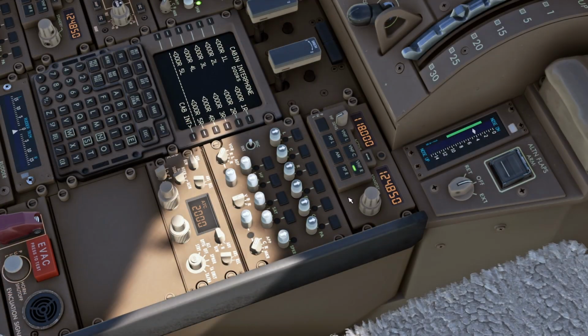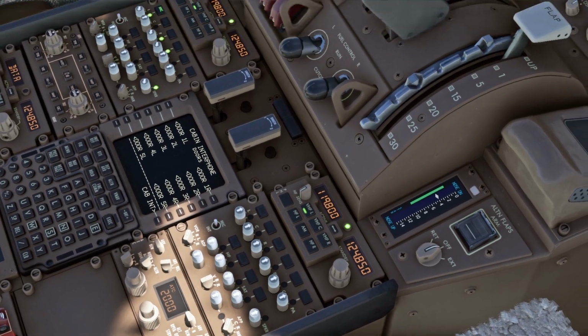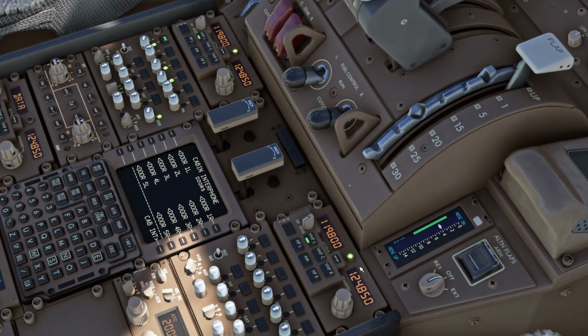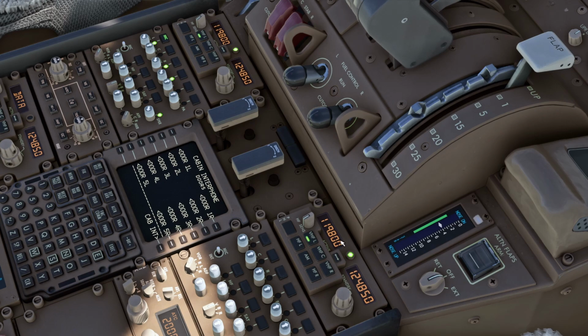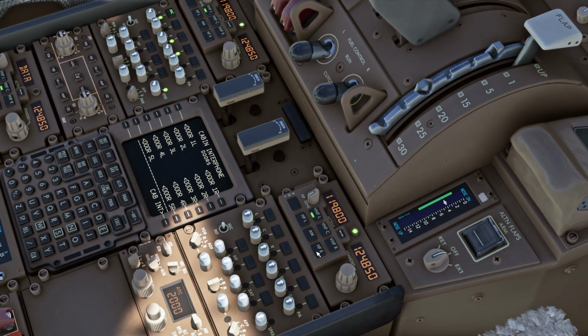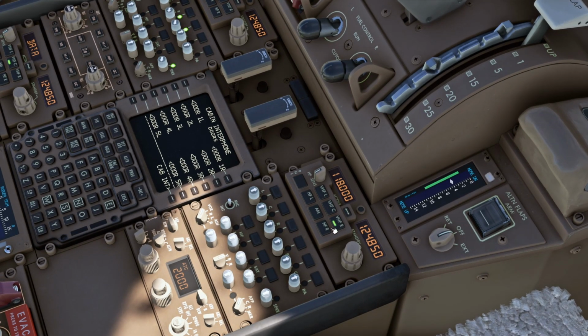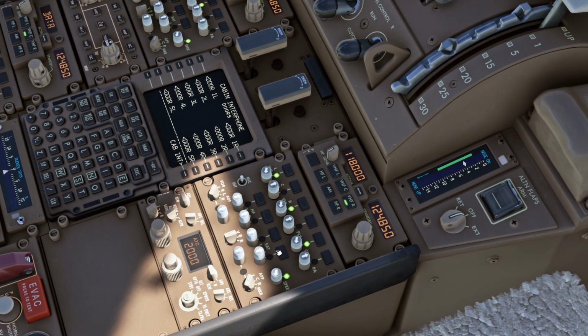Then the first officer radio tuning panel. Adjust to your liking. You can of course enter frequencies. You can also control an auto radio, so we would now be controlling the captain's radio, and as you can see, it would indicate with this light that you are tuning a radio that is not normally tuned by this side. So it's just a little reminder. For now, we're just going to leave it in VHF right, so we're going to tune our own radio, but again, just make sure you turn on the associated volume knobs and microphone selection if needed.